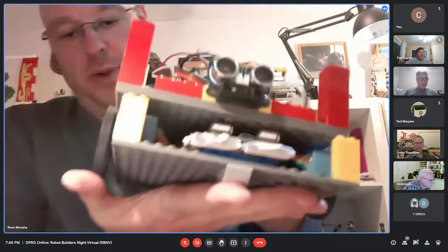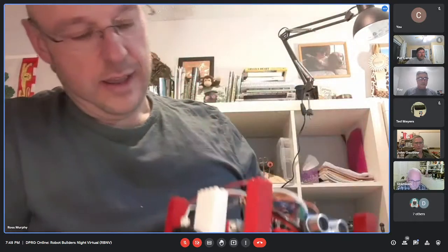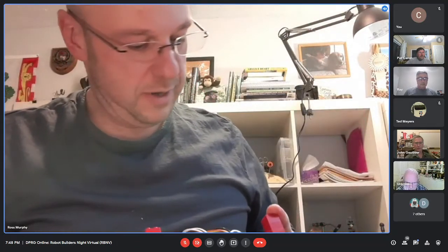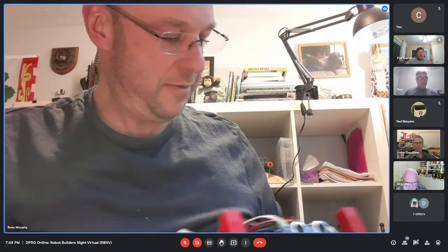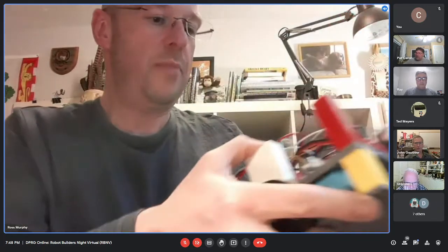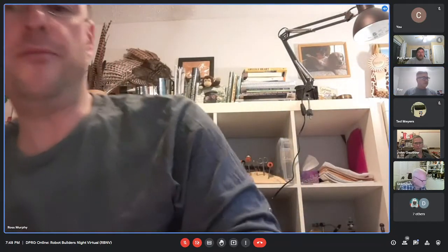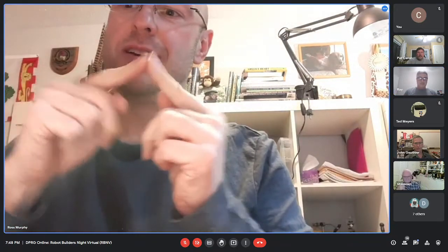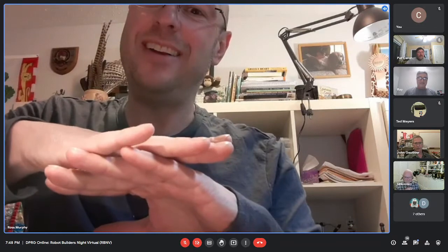I had the wires a little tidier, but I ran into the devil of a problem the other night where I had just had it working, and I went to demo it to the wife and child, and of course one of the motors wouldn't work after I put it back together, and I couldn't figure it out for the life of me. I had been soldering, but everything looked good, and I basically tore it all apart. Tore every connection out of it and went through it, and I actually had a bad wire. One of my PWM wires for the motor had an intermittent loss in it, and when you put the lid on it, you pinched it.